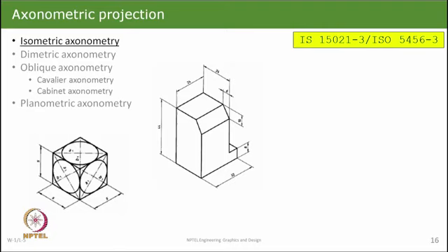We now go to the other type of drawings, which is called the axonometric projection, beginning with the first type, which is called isometric. What it does simply is that you have two axes, one at 30 degrees to the horizontal line and then a vertical line, and a cube is placed on this so that its dimensions, the way it is drawn, are equal in all three directions.